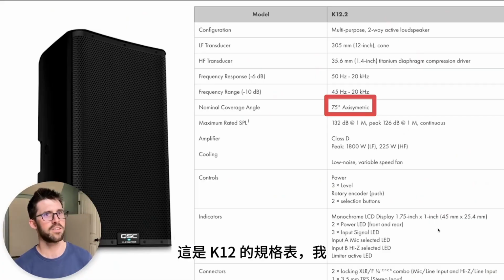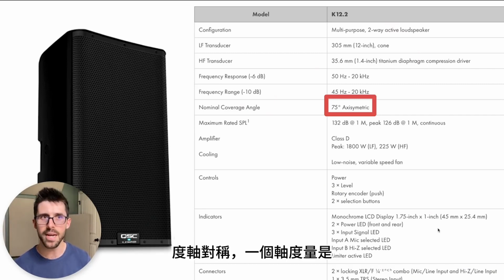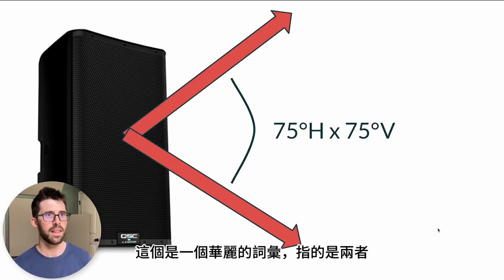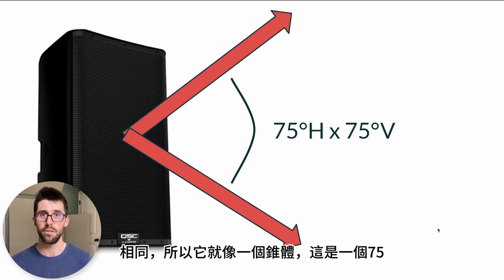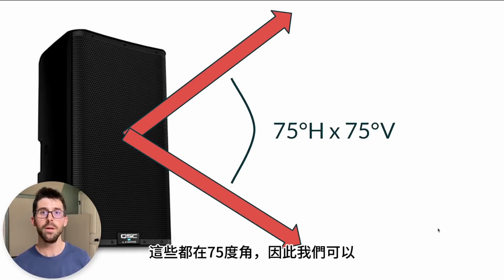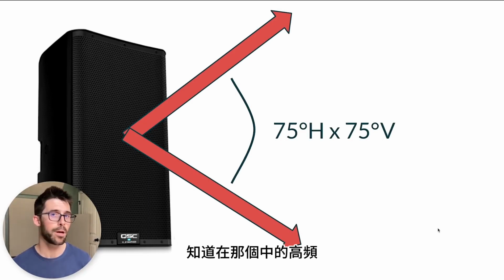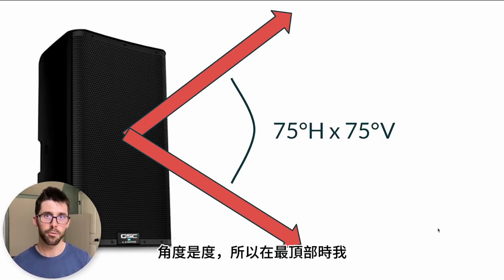So on a K12, this is the spec sheet, and I looked at nominal coverage angle and it has 75-degree axisymmetric. Axisymmetric is a fancy way of saying that both the horizontal and vertical coverage are the same. So it's like a cone, a 75-degree cone. Those red arrows drawn there are at a 75-degree angle. So we can know that the high frequencies in that speaker are able to be steered in a 75-degree angle.